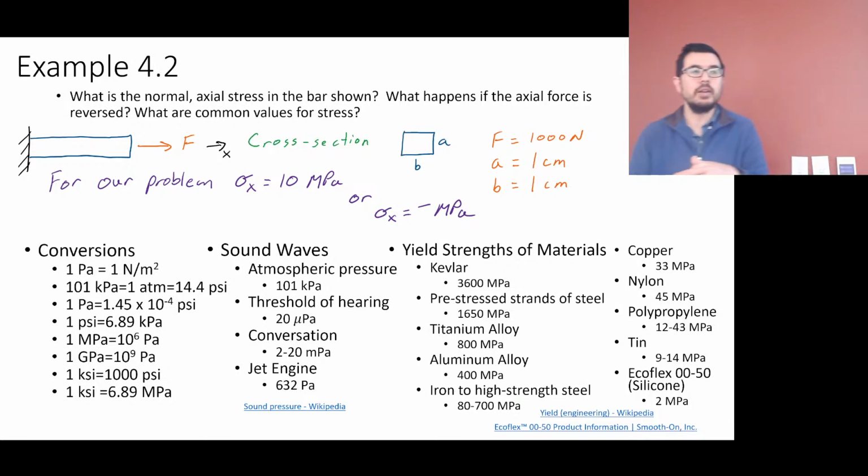Yeah. So these typically are done in tension. We'll cover this, but materials can behave differently in tension and compression. The metals and a lot of the plastics, materials that are kind of ductile, that don't just fracture real quickly like glass does, typically have similar properties in both tension and compression. But the ceramics and the glasses can handle more in compression than they can in tension. And it's not, how do you say it, it's not suave. It's not nice and easy and soft when it fails. It is